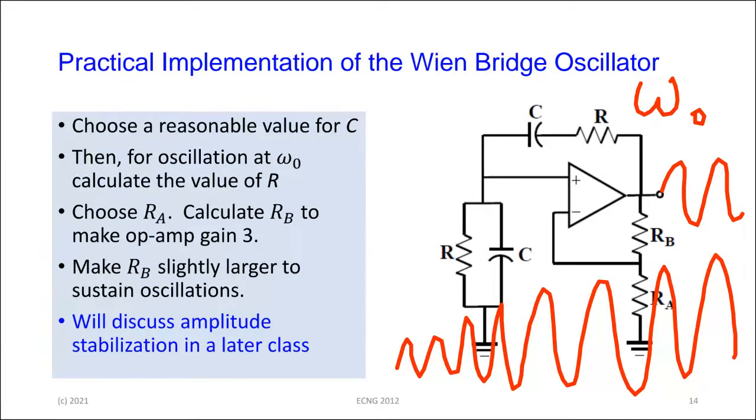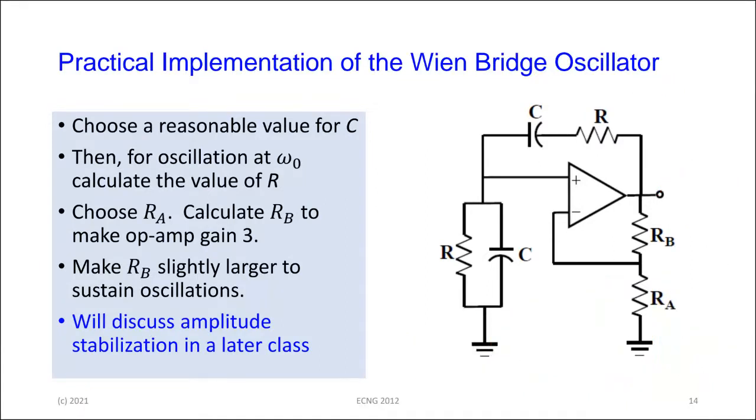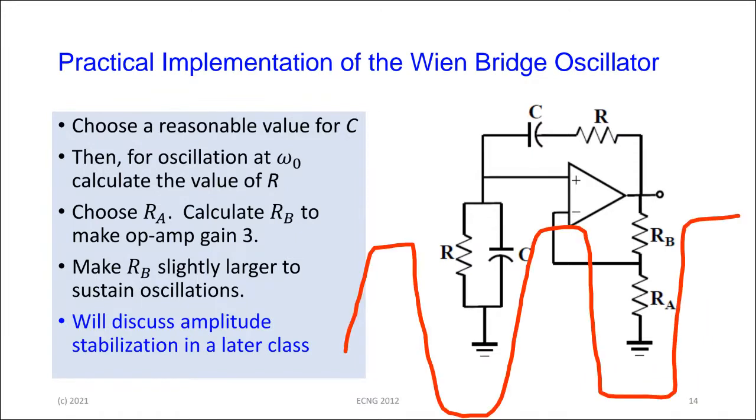And then, as it approaches the power supply, it will start to clip. So it will behave like a sinusoid and then start to clip. If you don't do anything about it, you're going to get something looking like this at the output.